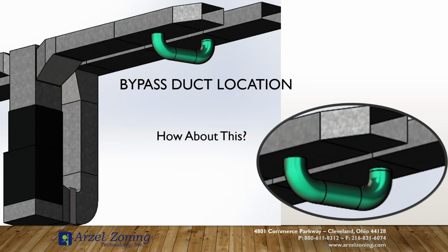So try to be about 12 inches away from reducers and fittings. Try to be about 8 feet away from the equipment whenever possible. And if you've only got 4 feet of pipe or 4 feet of trunk line before you shrink it down, then put it on the next section of ductwork. It's more important that it be about 8 to 10 feet away from your furnace than it is that it come off that first portion of duct whenever possible.